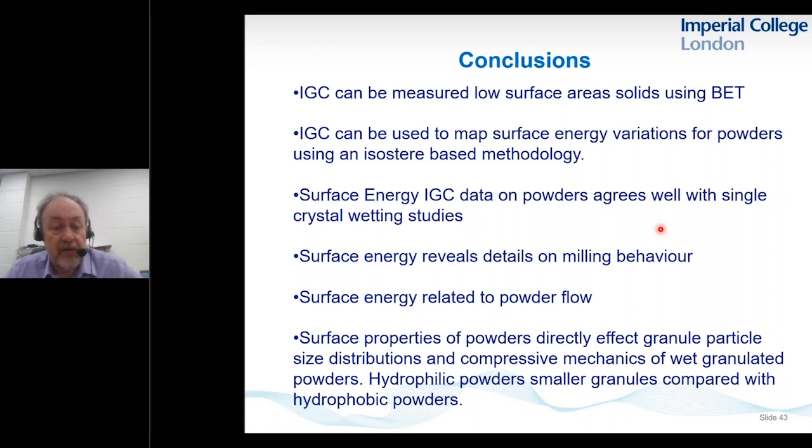The surface energy relates to powder flow, and the surface property of powders directly influences the granular particle size distributions and the compressive mechanics of wet granulated powders. And hydrophilic powders give smaller granules compared to the hydrophobic ones.